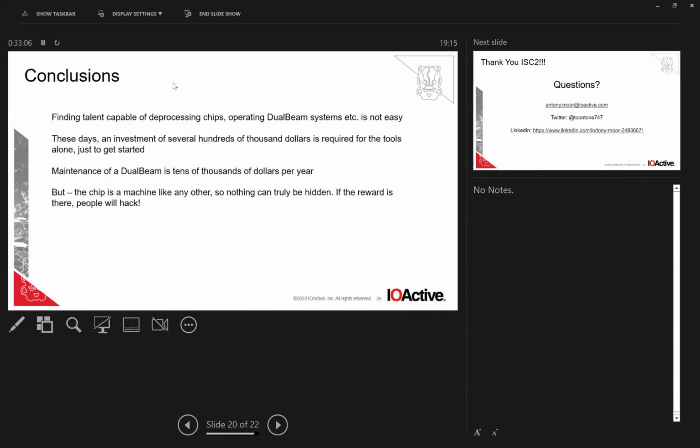Nowadays, the dielectrics or the insulators between circuitry layers have to perform much better, much better insulators, called low-K. So it's a very high performing insulator, and they're usually less like glass and more like a gel almost. These materials, and there are many, many more layers. So you look at a cross section and you see each layer between the circuitry is made up of several layers. It doesn't matter so much for the deprocessing because you can usually use the same chemicals to remove it. If it's an insulator, you'd use HF, hydrofluoric acid, or a plasma etcher, and it would do the same job.